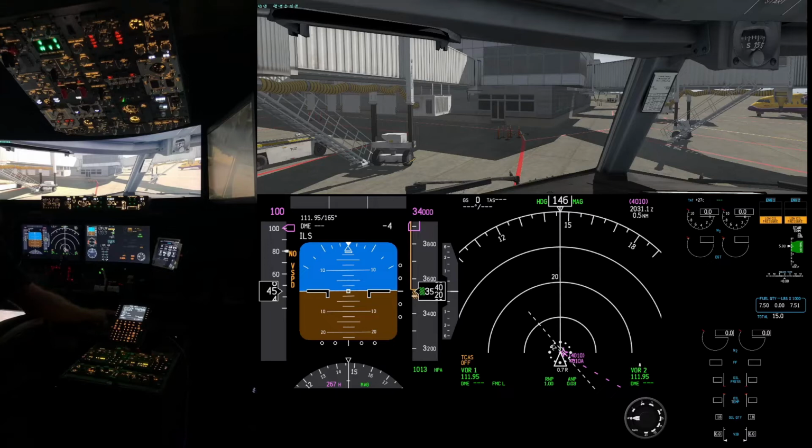And the cost index, which is how fast or slow I'm going to burn the fuel, today is going to be 18. We're going to be cruising at an altitude of 320. I put that in, and I look at the top of climb winds in my flight plan, and it tells me it's 261 at 050. I put that in with an ISA deviation of +6.